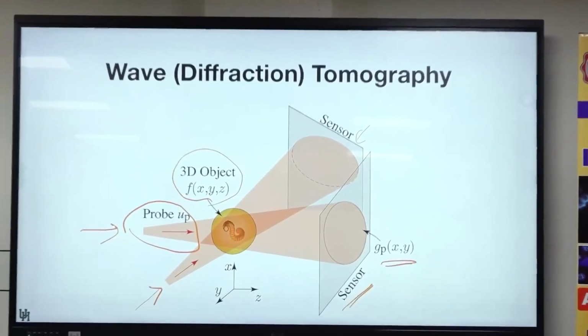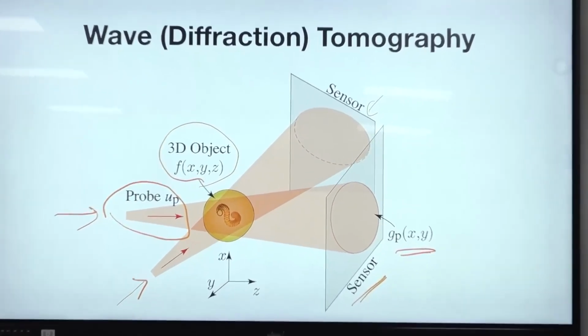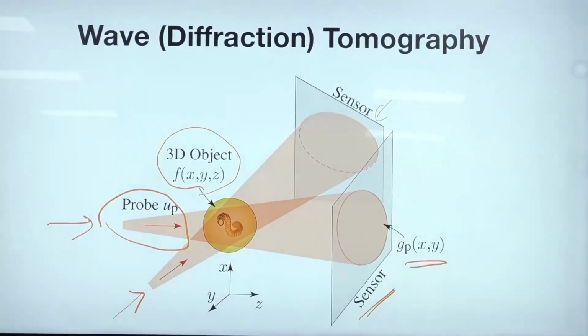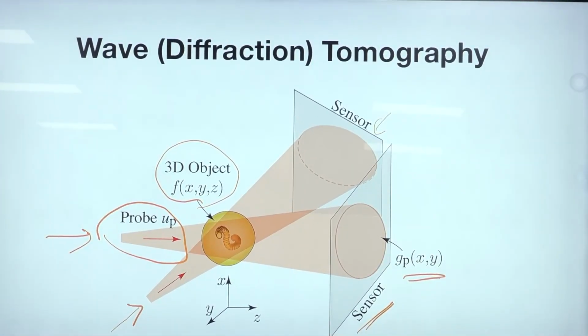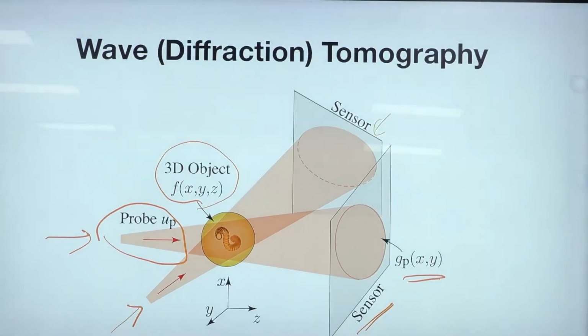Now the thing is, if all the other light in your room is visible light, then you can put a cutoff filter which removes visible light, and the sensor will only be sensitive to infrared. That way, even though the light is on, most of the light that reaches the detector would be infrared only, because you're using the optical filter to remove the visible part. So that way you can keep the lights on.